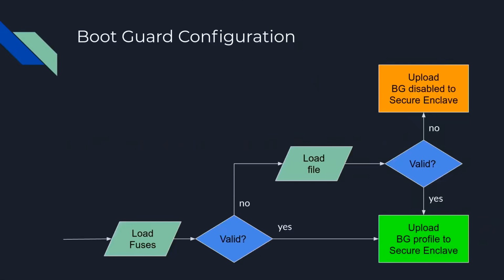Then Boot Guard configuration is fun because, you know, where they say they fuse in the keys, well, yeah, but the ME loads them from fuses and then manually loads them into a register. So if you have code execution on the ME before it does this, you can just load your own values and you can run coreboot even on a machine that has Boot Guard.